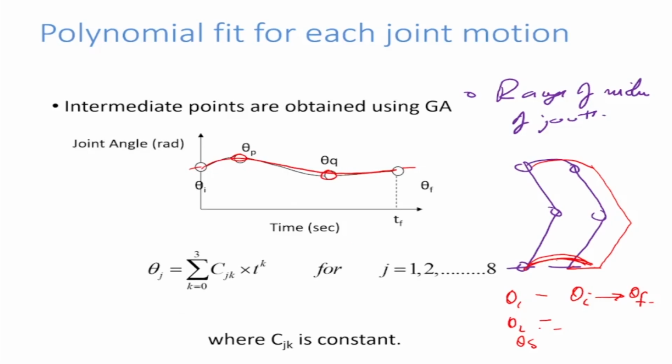Okay, so in the previous case, I was optimizing the foot trajectory, whereas in this case, I'm not optimizing the foot trajectory, I'm optimizing the joint trajectory at the joint level. Would they be the same? Would the answer be the same? Yes, the answer would be the same, because the torques in both cases have to be minimum. It'll give you the same answer.